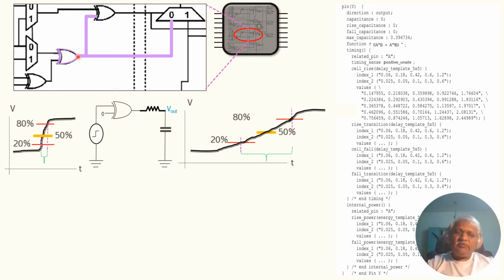And whether we need to increase this drive strength or add buffers here also depends on the optimal selection of the design. So again, power, area and performance all come into play. That is why the design rule constraints play a great role in each step, guiding the synthesis tool to make the right calls.